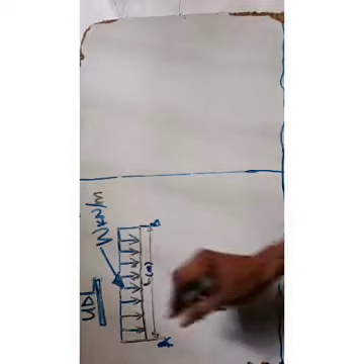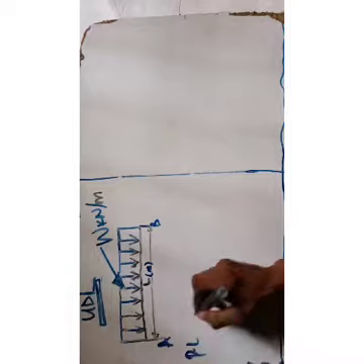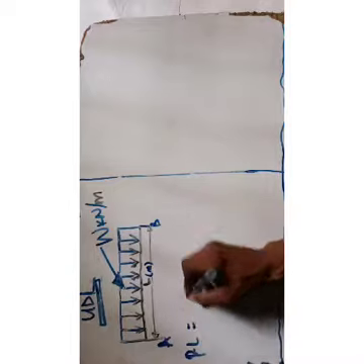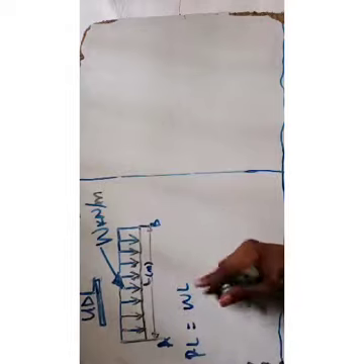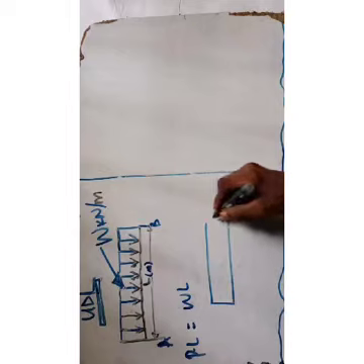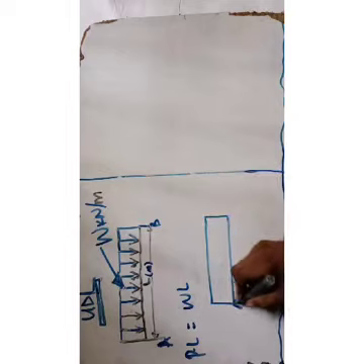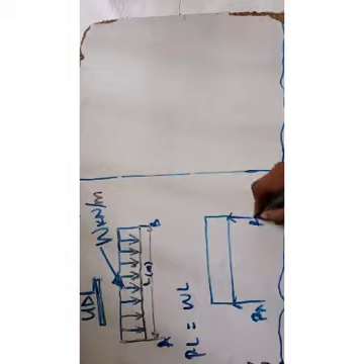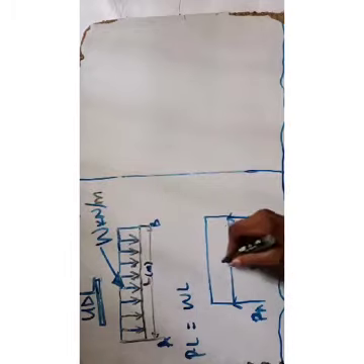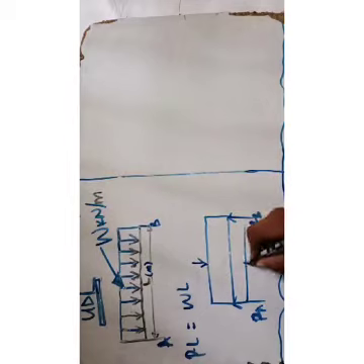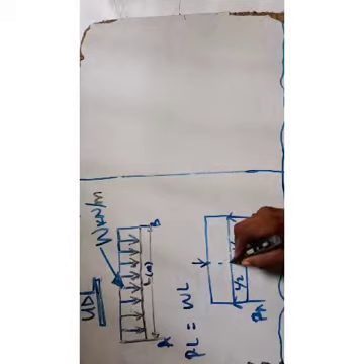So for example, you want to solve this. Convert this to point load, and that will be this times the length, WL. When you convert to point load, rather, it will be like this. That is the reaction A, reaction B. Then this guy would come, and this will act at the center. It will automatically act at the middle. And if you remember, the total length is L. So this half will be L over 2.